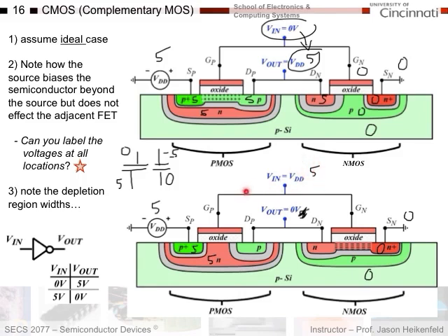Well, if I've got 5 volts at the input, and I've got 5 volts here, I've got no net voltage drop across this gate here. Well, if I've got no net voltage drop, then I get no charge, right? No voltage drop across a capacitor, no charge. If there's no charge, then of course I've got no net charge here. I get no p-type channel to form. And remember, out here, yeah, you've got electrons, but for every electron, you've got a phosphorus atom. So the net charge is 0, which makes sense. Okay? And so that means this 5 volts can't make it to here.